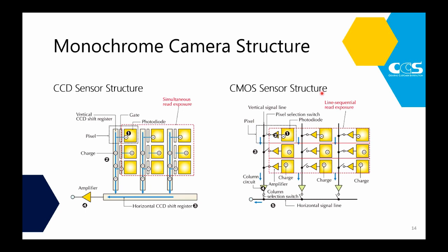So in area scan cameras, there are different camera sensors that you can have, especially for monochrome cameras. There's the CCD sensor and the CMOS sensor. The CMOS sensor is definitely going to be more common in machine vision. It offers higher dynamic range and lower cost. It does have a little bit more noise than a CCD sensor, but it has a lower cost and a faster frame rate. It's definitely getting closer to the quality of a CCD sensor, but not as great for low light applications, for things like astronomy and life science. But for the machine vision industry, most of the sensors you come across are going to be a CMOS sensor.